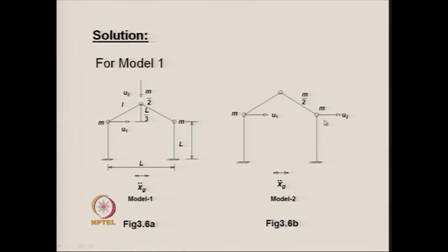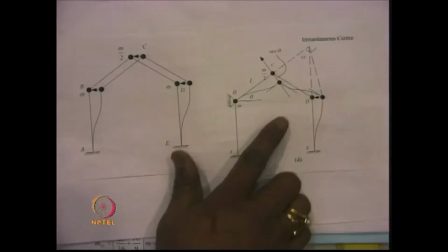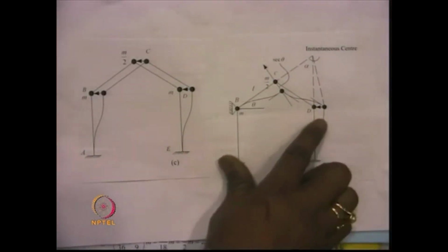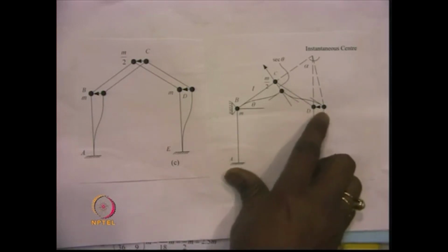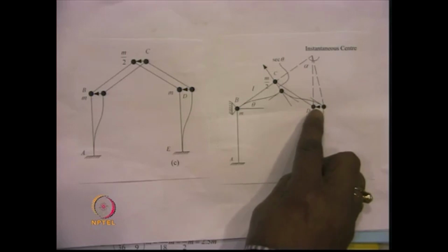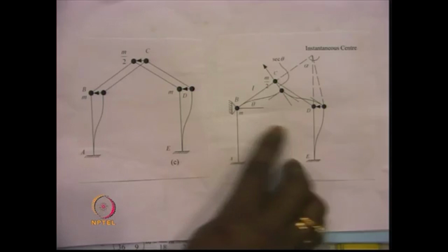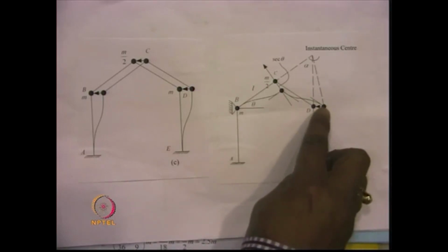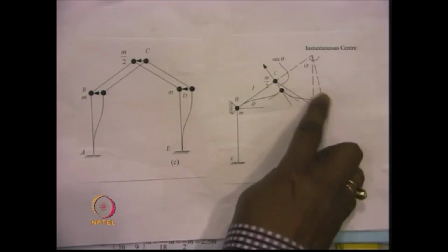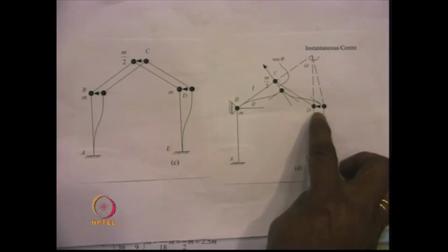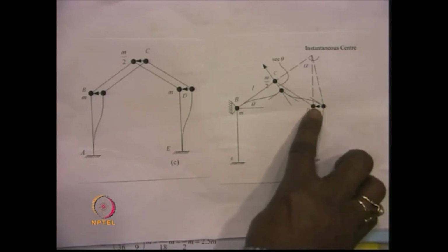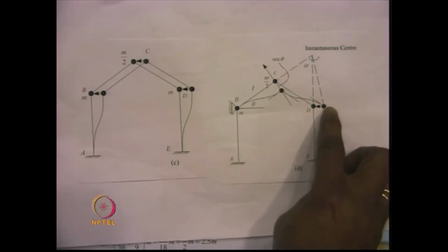And for that one can straight away go to this particular figure, say that in the case when we are considering this degree of freedom, then we give a displacement here such that unit acceleration is induced over here, and at this point we lock it, and because of the unit displacement which is given over here, this point will move down, and we will have forces which will be induced over here, and this force will be resolved or will be equal to the force which is induced at this particular point because of the unit acceleration induced here.